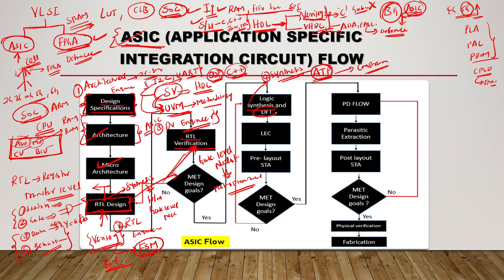And next you have DFT engineers. What will these DFT engineers do? They will give some scan, which is like testing. DFT is nothing but testing only. So there is scan chain, BIST, built-in self-test. They will give some test vectors to your design to check whether your design is meeting the specifications or not. So for this you need DFT engineers.